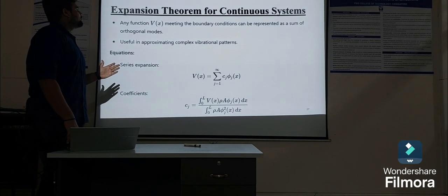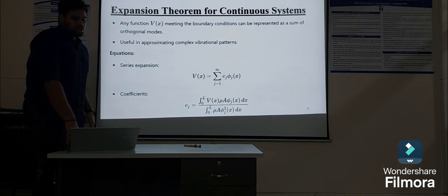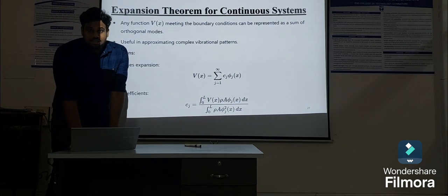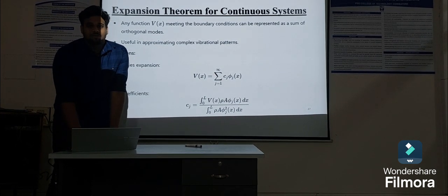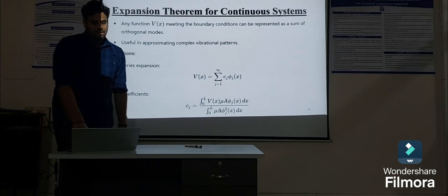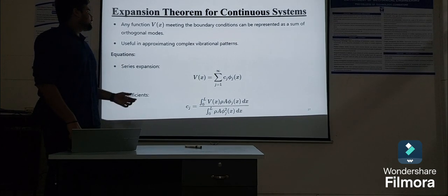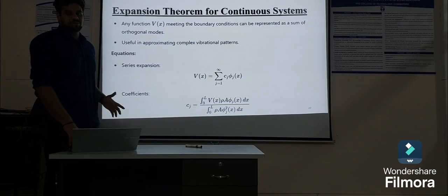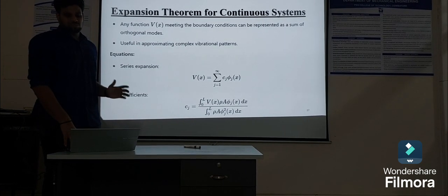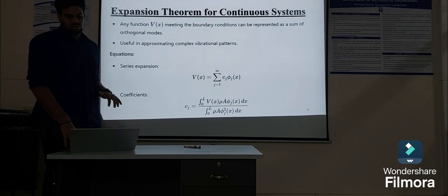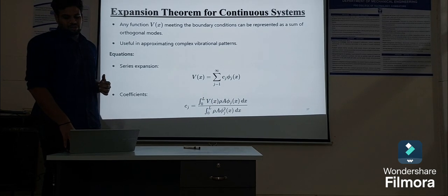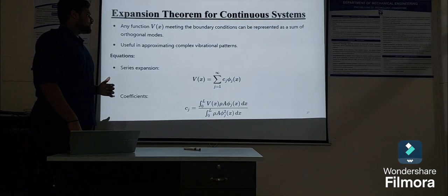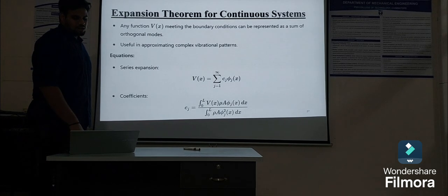Let's see the expansion theorem for continuous systems. Any function v of x meeting the boundary conditions can be represented as a sum of orthogonal modes, useful in approximating complex vibration patterns. The equation for series expansion is v of x is equal to summation of j equal to 1 to infinity c_j into psi_j of x.